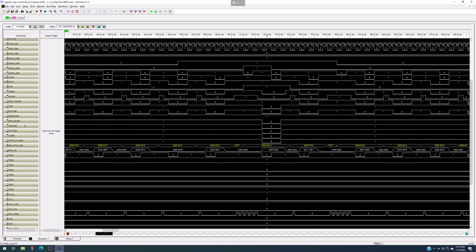And this is now work I have to do, especially as I start picking up the speed. I know the system runs fine at the fastest speed I can run with my little 555 timer, which is about 250 hertz right now. Because I run out of a 555, I go through a flip-flop. So it really cuts in half whatever that 555 was configured to output.